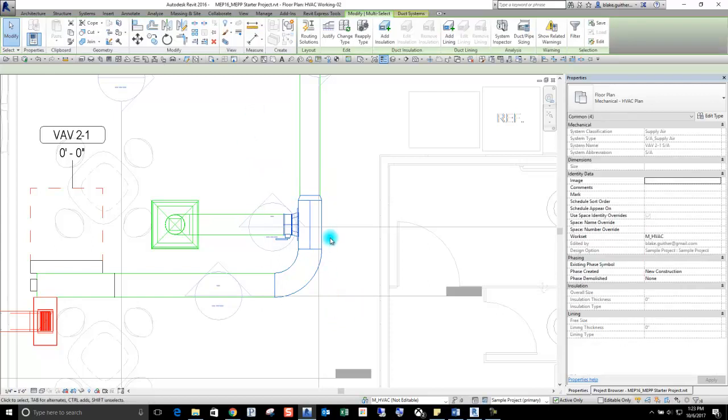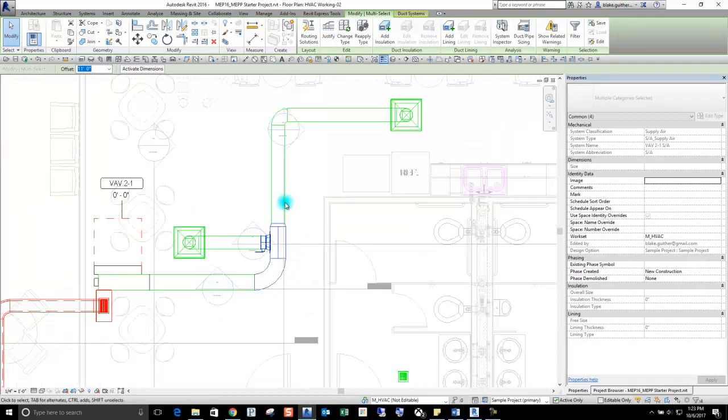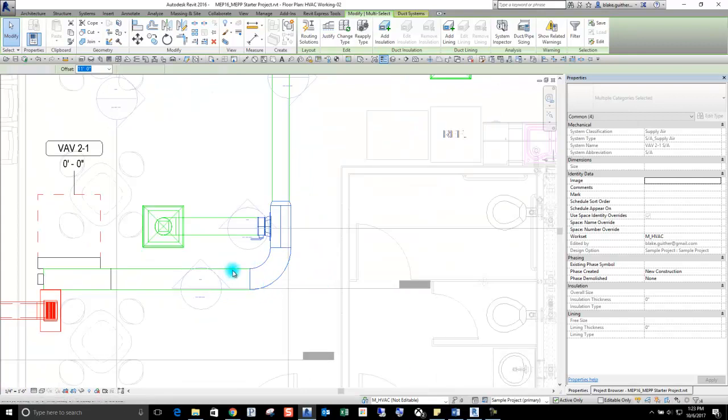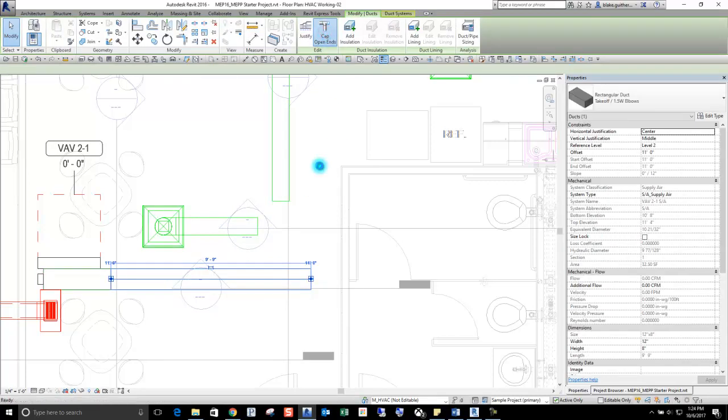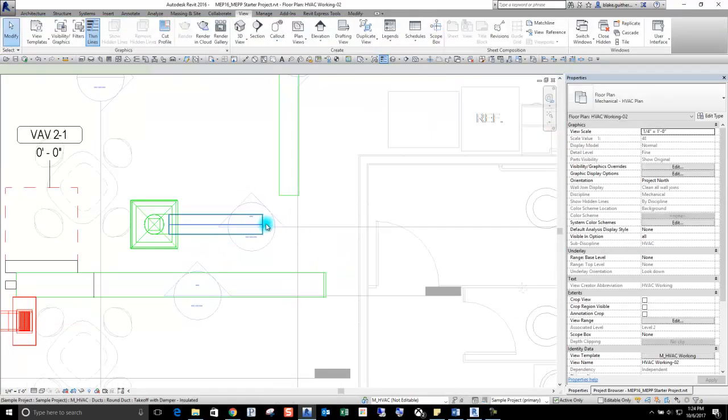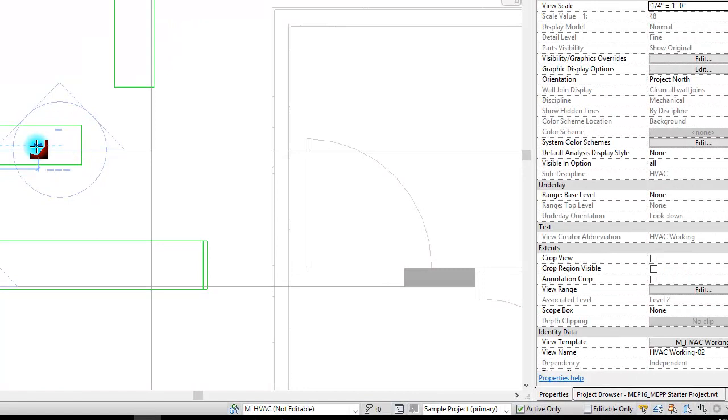So like in this particular situation, maybe instead of doing this, maybe you want this duct to come over and be capped. So we can cap that duct. And now we can just drag these branch ducts into here just the same and show the dampers that way. So like this given duct, let's stretch this back a little bit.